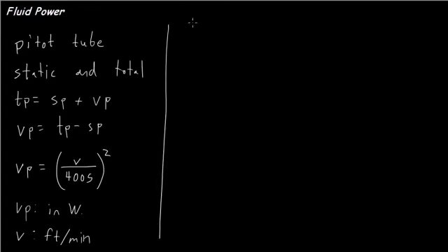Okay, a couple of very important working equations with fluid power. Just like we saw with mechanical power, these are equations that include unit conversions right in the equation. Saves us a little bit of time as long as we're using the proper units for those quantities. Okay, for these equations, you should know that when we talk about pressure, we're talking about total pressure of the fluid.